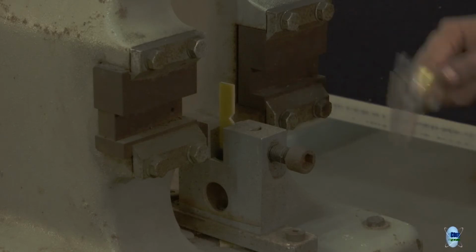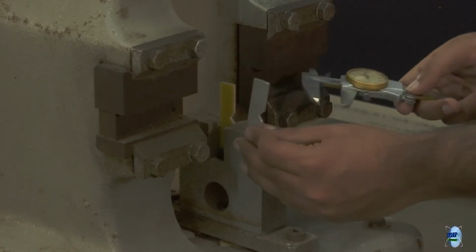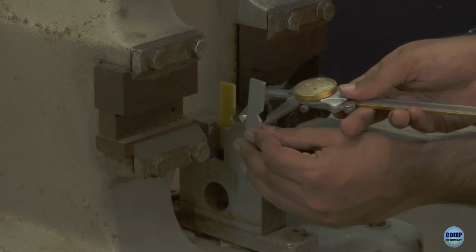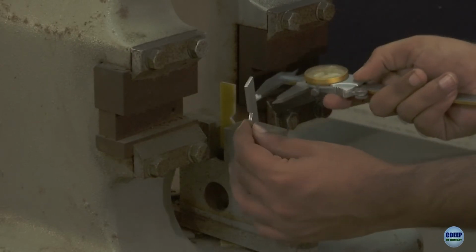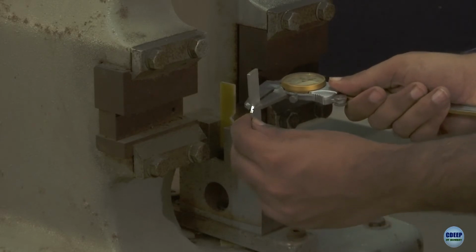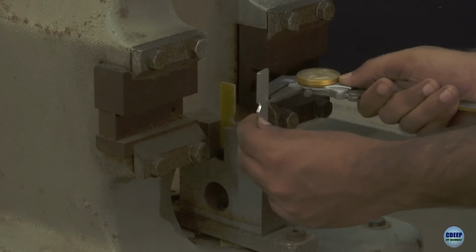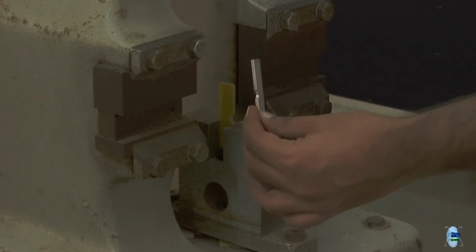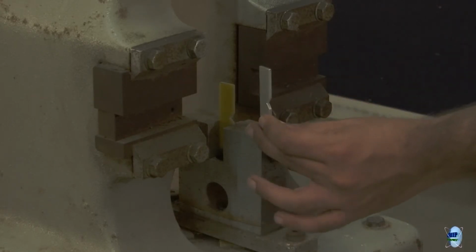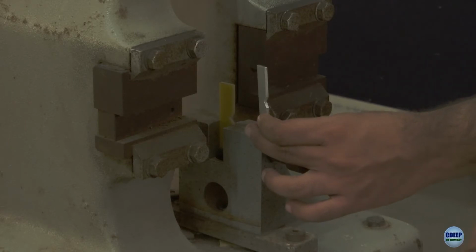Please take note, before breaking it, for every single specimen, we have to take the measurement of the length of the notch and the width of the notch, and that is what will give us the area. Each specimen is manufactured, so of course they will not be absolutely identical, so you have to do it for every single specimen on its own.